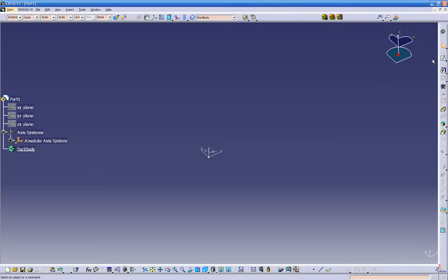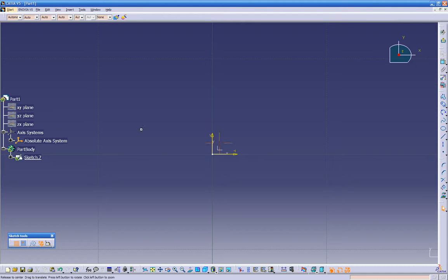Let's open a new sketch again. Let's go to plane. It's going to ask you down here, select a plane or a planar face or a sketch. We can click on one of those planes. We can click on XY over here, XY plane. We can see it on the top right here. So if we click on the Z, it's putting our part on the XY plane. Or we can click on XY plane up here, which is the same thing. Now we're back on the sketch.